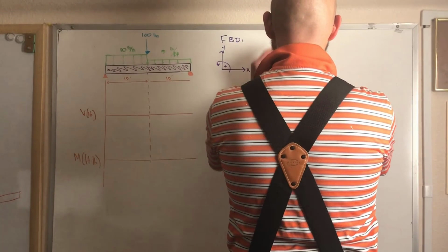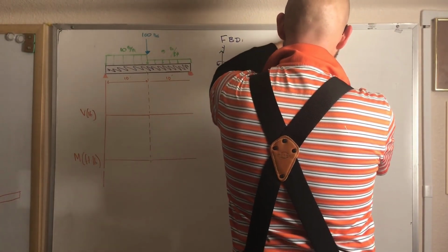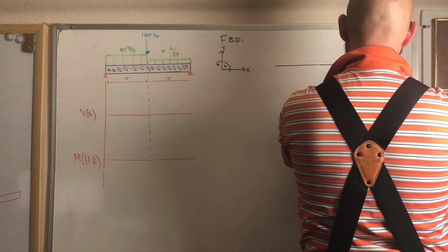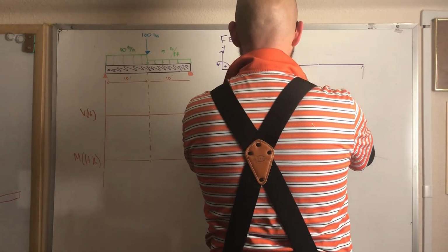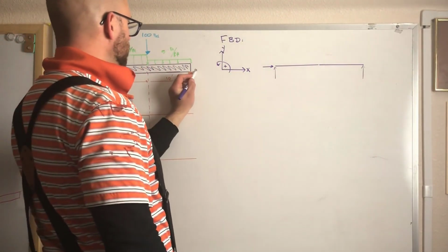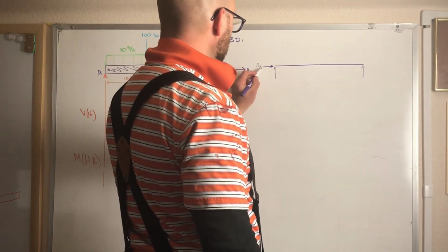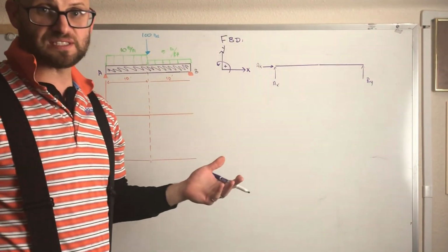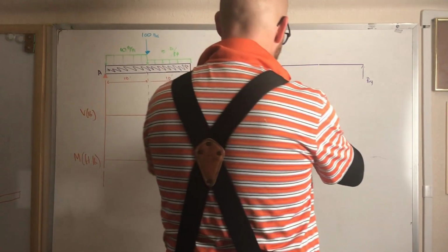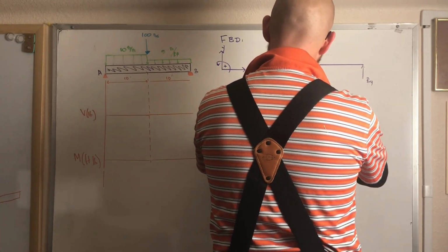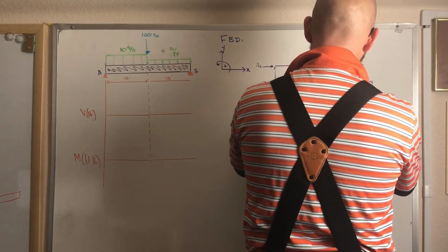All right, and now we're going to do our simply supported beam, and to a certain degree, it's redrawing everything that we just did, but now with the proper arrows for the reactions. I'm going to call this A over here, and this B. So this is AX, and this is AY, and this is BY. Now you should be seeing the same thing that we did before. This is not any different than the procedure that we took. It's just now there's a certain accountability for our math.